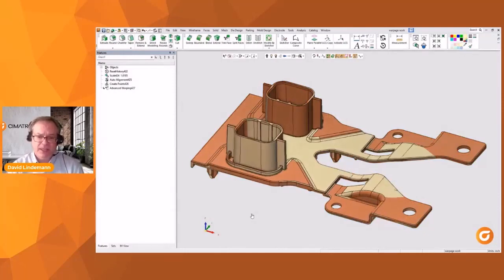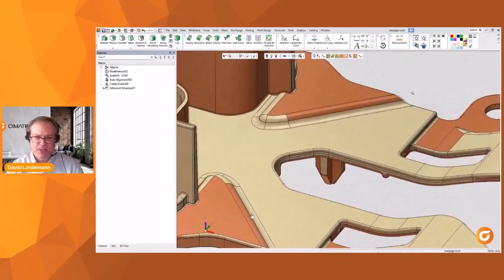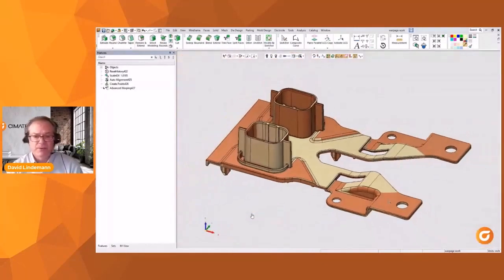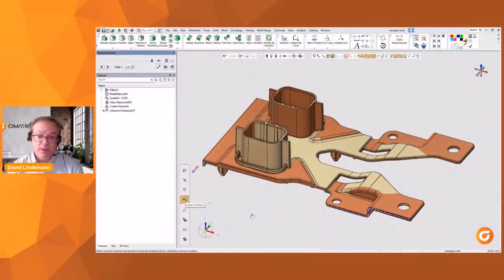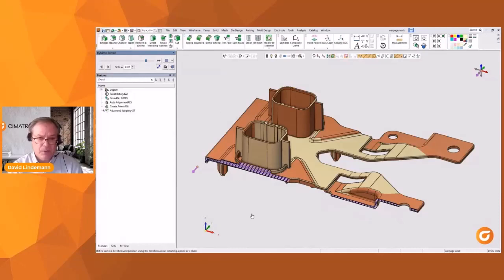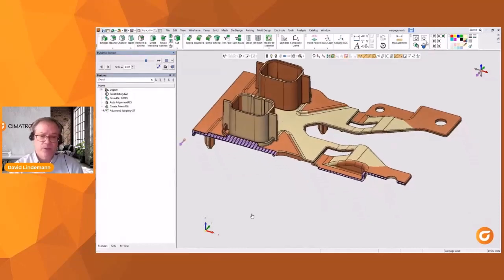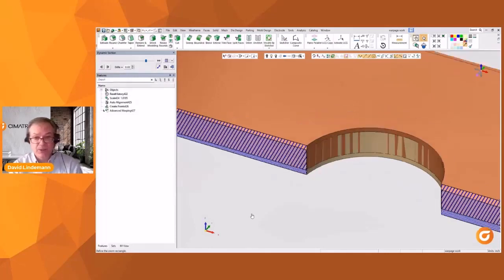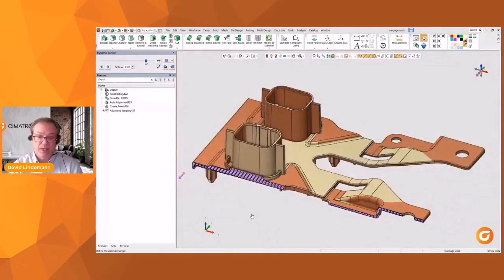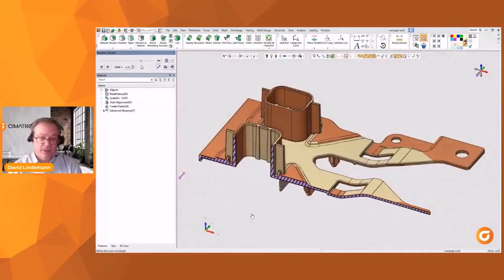So I'm going to take the original CAD file, and we turn it this yellowy color here, so I can see that versus the file that's got the compensation in it. Maybe there's areas in the geometry I need to adjust. One of the things I need to look at is hole location. I want my holes to still be in the pull direction. So am I still on location where maybe existing core pins already are? Here I could see with the colors bleeding through between the two that, yes, it's held those hole locations. So the warpage hasn't affected it that drastically.